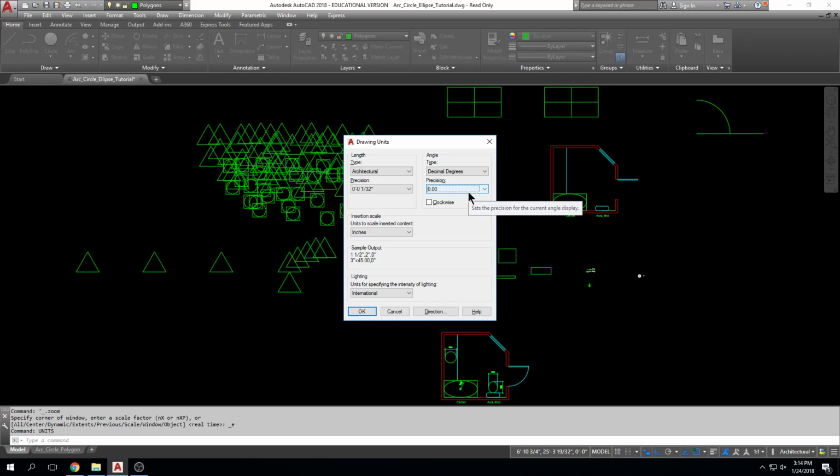Architectural units are different than decimal units, right? We talked about that. Your very first assignment was in decimal units, and even though you input it with coordinates, it was in the format of 1.00 or 3.04 or 2.63, right? So those are decimal units, and they're decimal inches, okay? Decimal inches are 12 times smaller than architectural units. So if you drew something in decimals and drew it all very nicely, it would be proportionally correct, but it would be proportionally 12 times smaller than an architectural drawing.